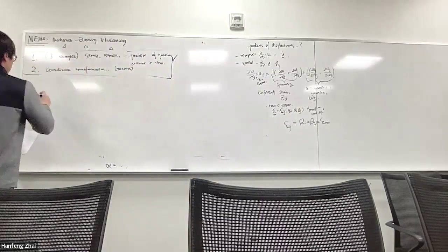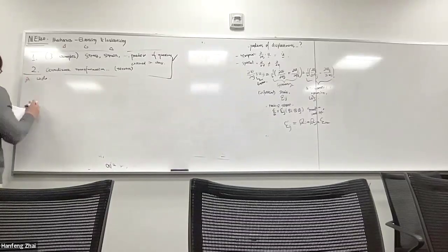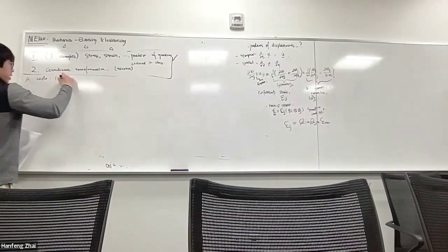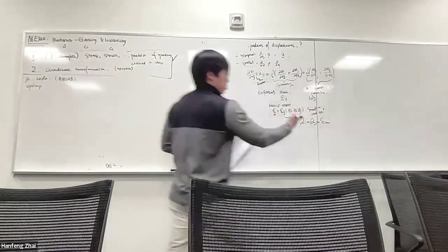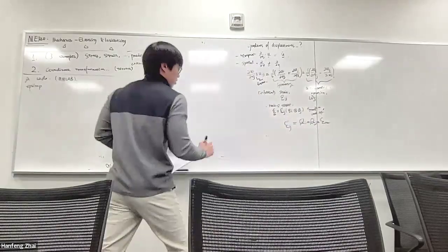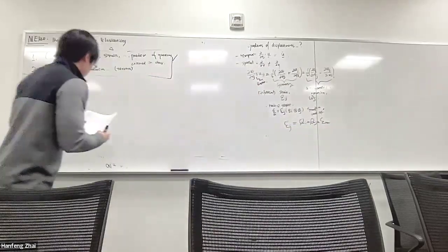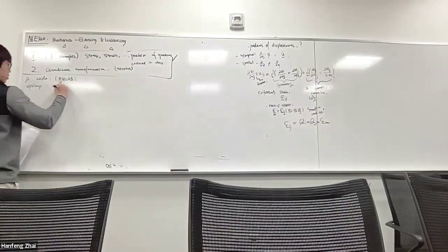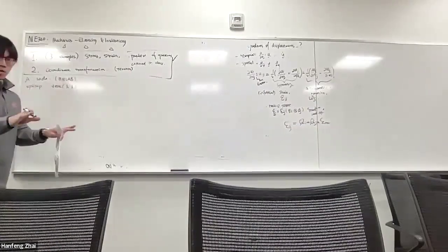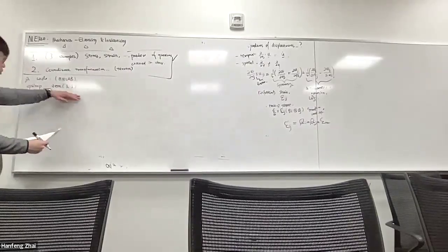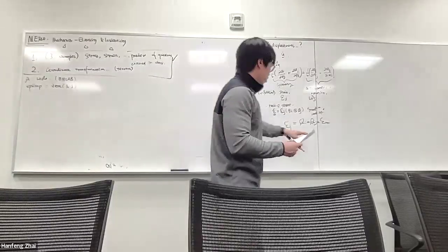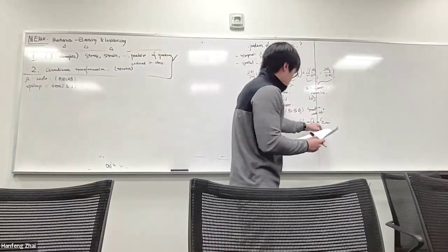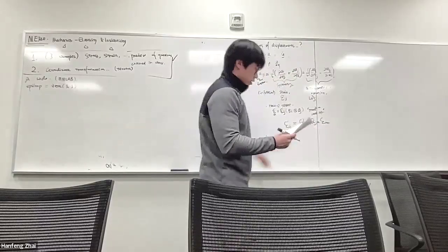So in code, let's say in the case of MATLAB, I can do epsilon prime, because transforming epsilon mn to epsilon ij prime, transforming index n to ij prime equals 0, so 3 by 3, assuming we're living in a 3D space, and it can be represented in the form of matrix. Since there are transformations from n to j, m to i, there are 4 indices involved.